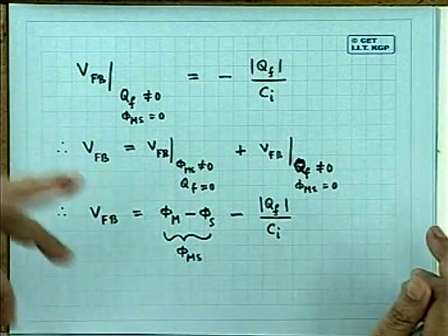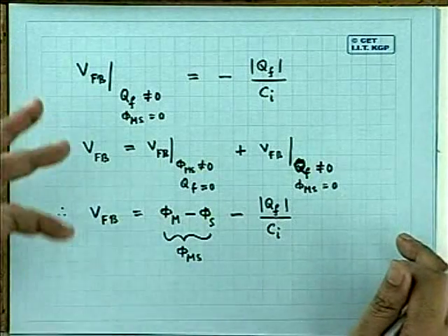If you are quite experienced, sometimes in certain cases the QF may be negative. Bare silicon, or nitride grown on silicon, has a negative QF. In that case, it is better not to use the modulus. But because in 99.9999% of cases the oxides are dielectric, I have kept it like this. This is easy for your formula, for your computations.